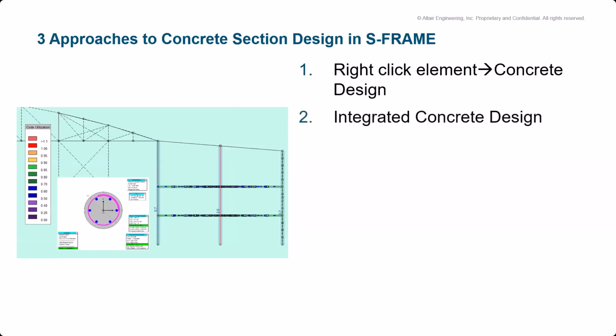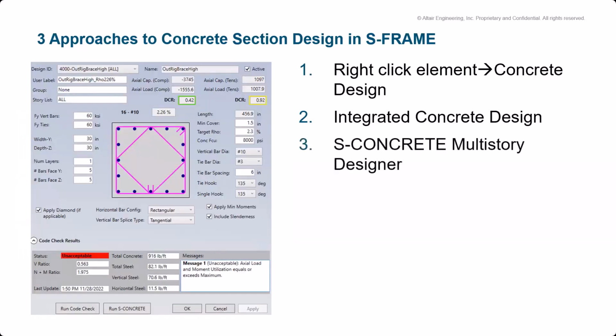This is assuming that you already assigned the correct materials and sections, right? So this is integrated into S-frame. It will allow you to open up the S-concrete interface directly from any one of the members. This uses S-concrete's capabilities member by member. And the third option that we are going to be covering today is the S-concrete multi-story designer, or MSD for short. It uses S-concrete's design engine in the back.